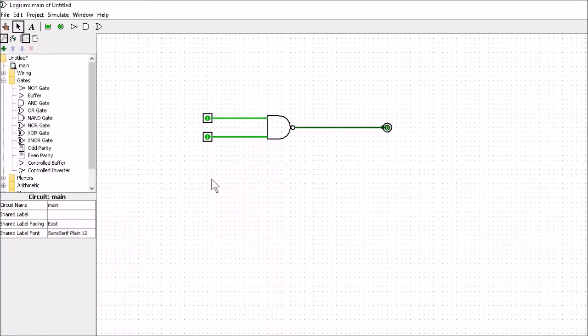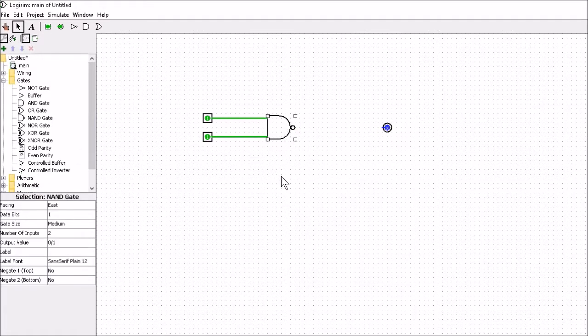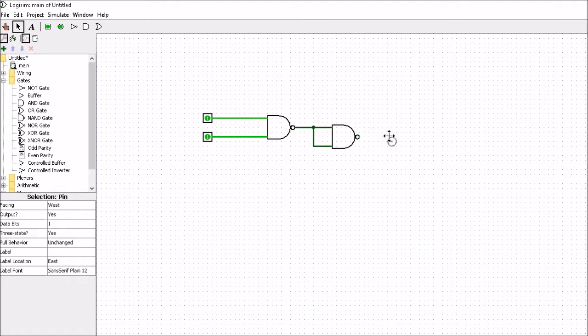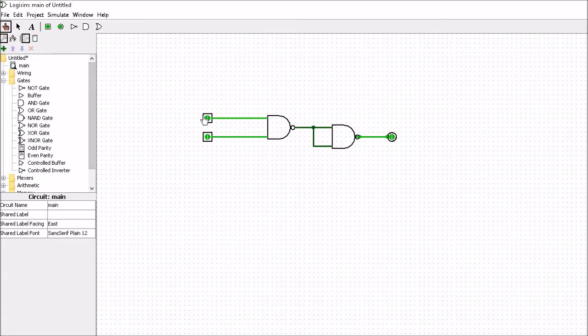Now we can generate an AND gate from the NAND gate by inverting the output. But we know how to invert the output. We can just use this little NOT gate here. We've already designed a NOT gate using a NAND gate. So we can go ahead here and produce this NOT gate, and we can connect this to our output. So what we should have here now is an AND gate. Let's go ahead and see if that's what we have.